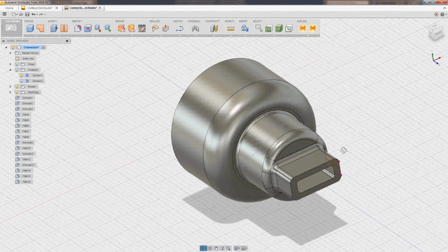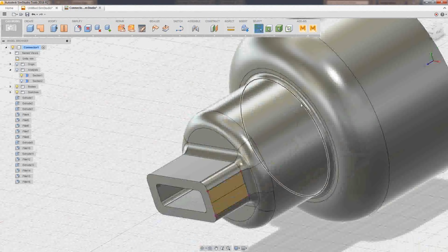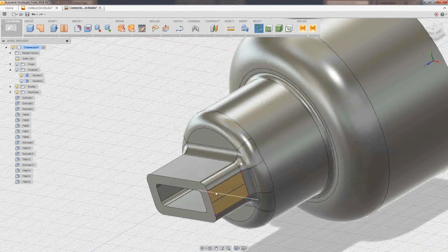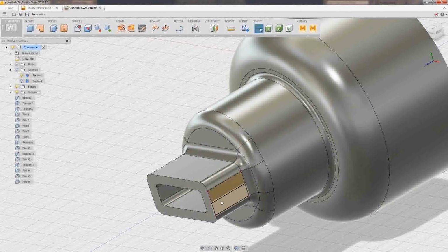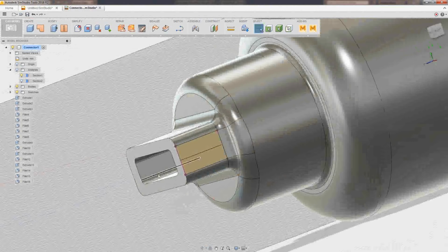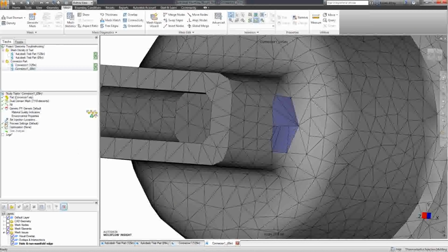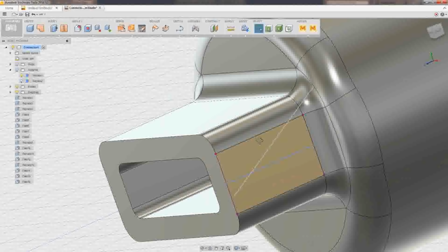And if we look at this part, you can see here there's something strange right here. It's a different color. Usually when you import a part and it's all one body, it all looks the same. So here, because it's a different color from the part here, it means something else was happening whenever you were modeling it. So let's look through it. Now, this is something that I just added after the fact. It doesn't necessarily represent the mesh issues that we were seeing here, but it's something similar that could happen whenever you're troubleshooting those types of mesh issues.